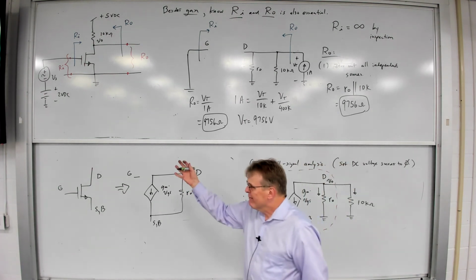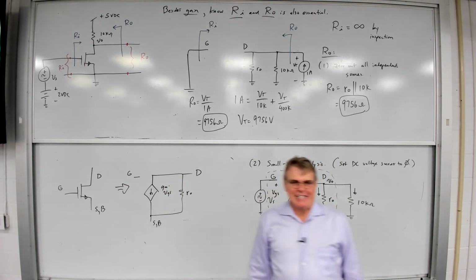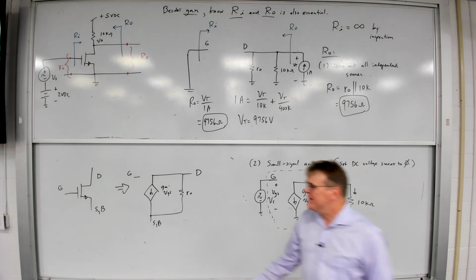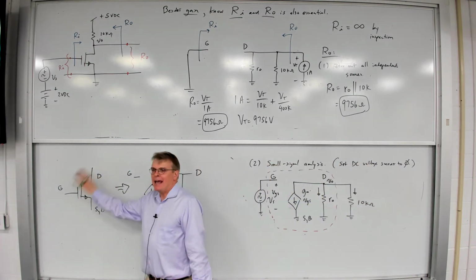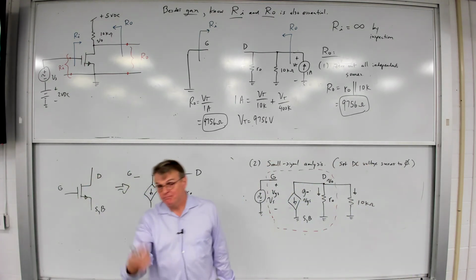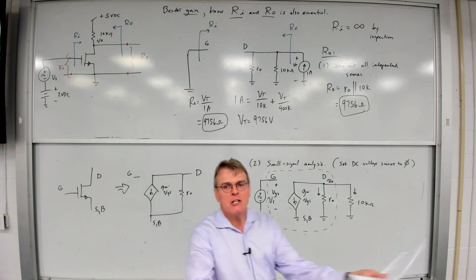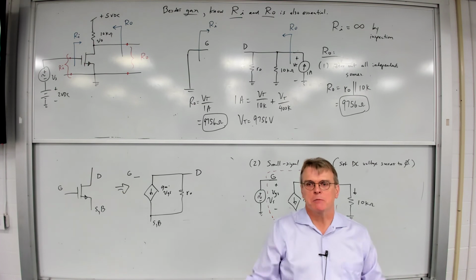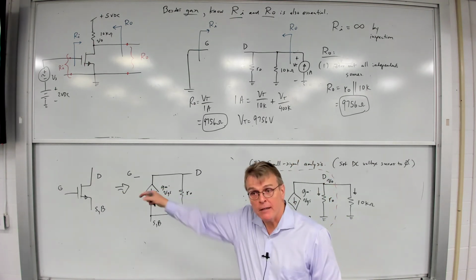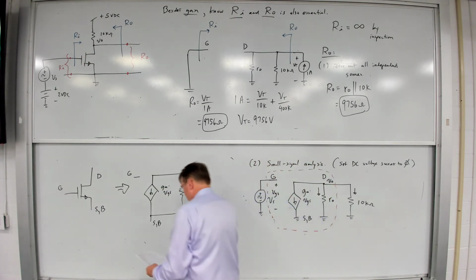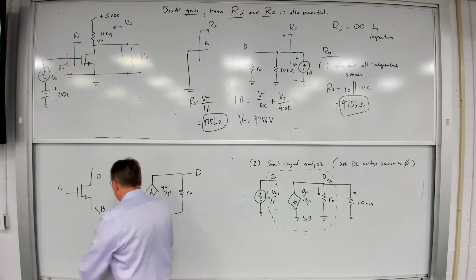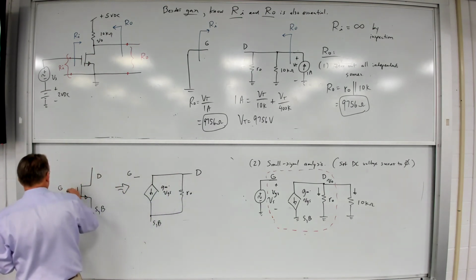But you know, real MOSFETs are a lot more complex than this. What does any real-world component have? Parasitic capacitance, right? We talked about that. Any conducting materials will have capacitance between them. Well, it turns out that's absolutely the case for a transistor. It turns out that there are actually two capacitances we need to care about very much.